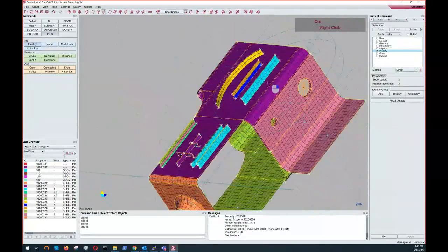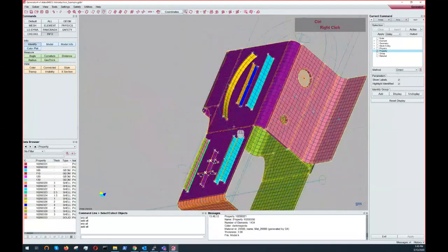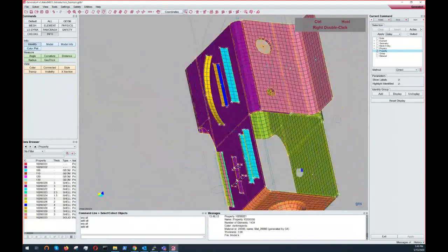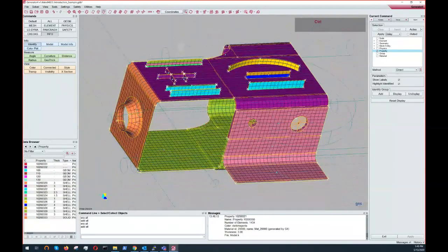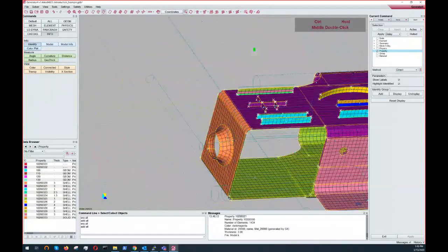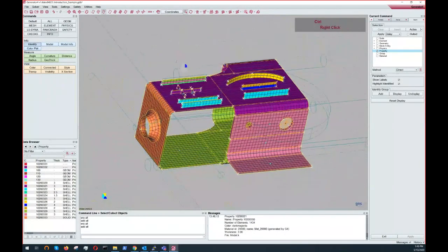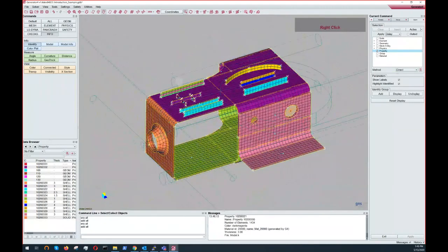Where you click at first is where the rotation axis is taken. And then with Control and middle mouse, you can move the model. That's for the model moving and so.